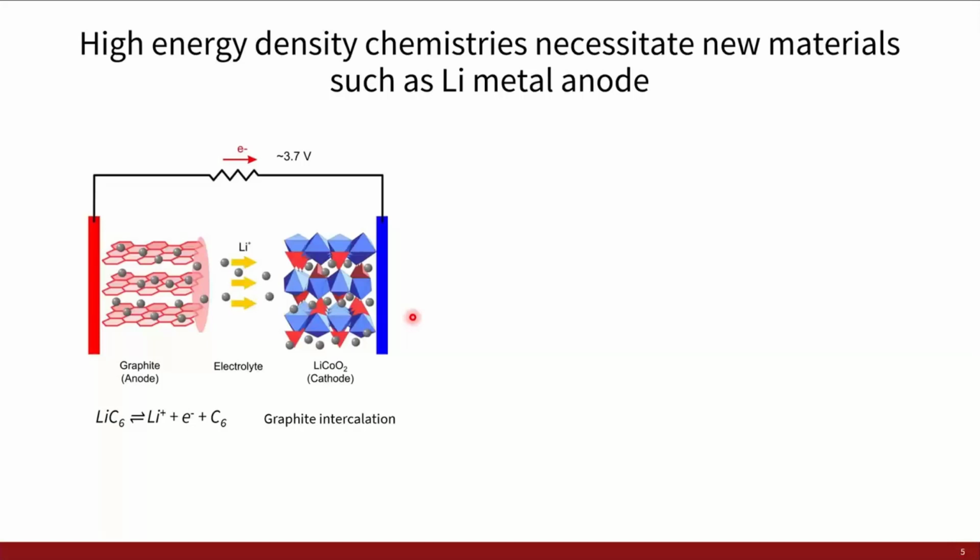A lithium-ion battery works basically by storing lithium ions between an anode, which is the negative electrode of the battery, and a cathode, which is the positive electrode. Lithium ions are shuttled between a high chemical potential state, which is storage in the anode, and a low chemical potential state, which is storage in the cathode. By shuffling the lithium ions between the high energy state and low energy state, we can store electrical energy and get it back on demand.